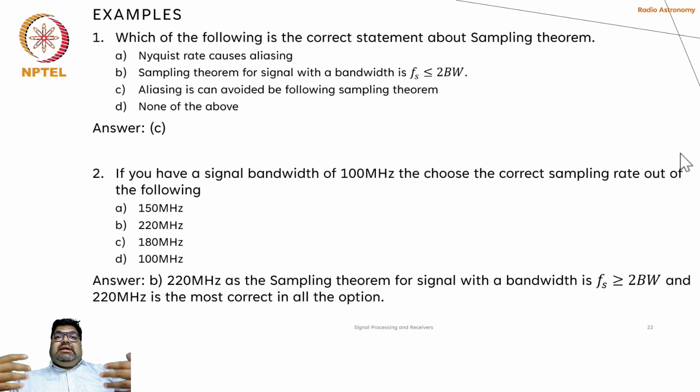We can transport the signal quickly, we can store the signal properly, etc., without loss of the signal, without other interferences, etc. However, when you are converting a continuous signal to a discretized signal, you should also make sure that it is sampled at a particular rate that is given by the Shannon-Nyquist sampling theorem.